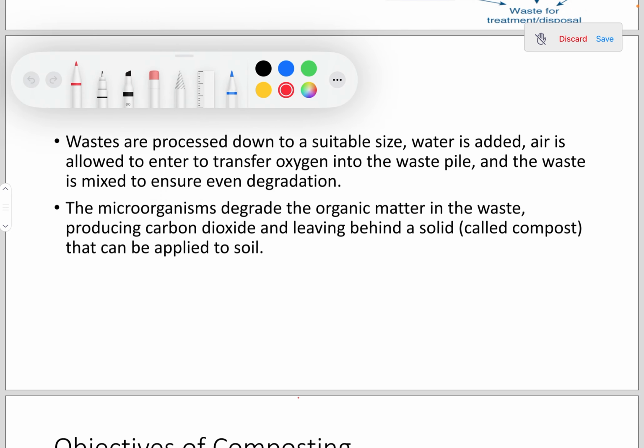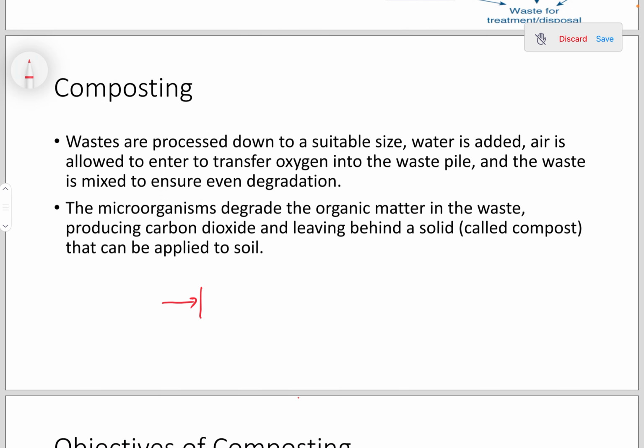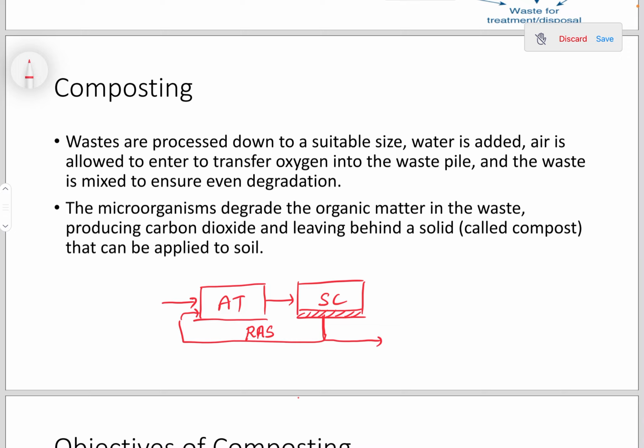The engineer told us about the process coming to Slabiya: the aeration tank, where the biological treatment happens inside, then the second clarifier. Some of the sludge settled at the second clarifier is recycled back to the aeration tank. Remember what was the name of that? Return activated sludge. And the remaining is wasted as waste activated sludge, and the clean water goes to the remaining process, whether it is disinfection, filtration, and then later on ultrafiltration and reverse osmosis.